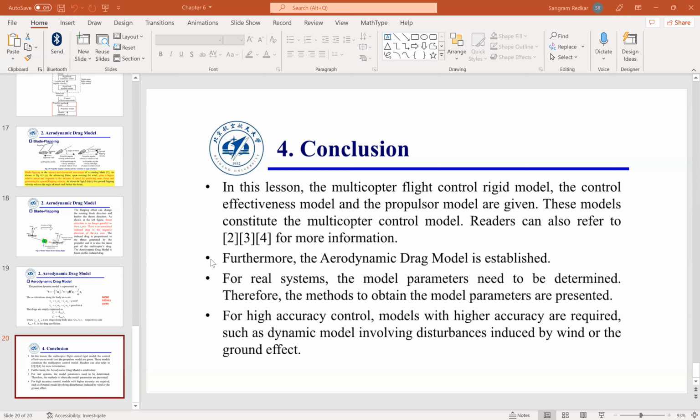Understanding this is super important. One thing, this transformation is an orthonormal transformation, which means inverse is equal to transpose. So if someone says, hey, I don't like the velocities in inertial frame, I want to go to body, then rather than taking this ERB from here, I would do RBE, and then I would still write the equation. Everyone understood this?